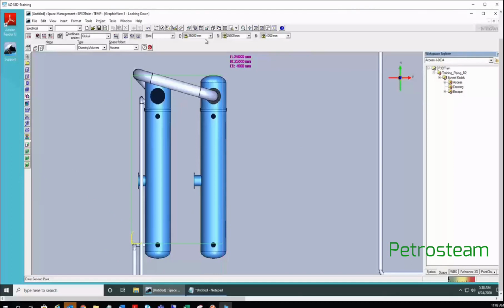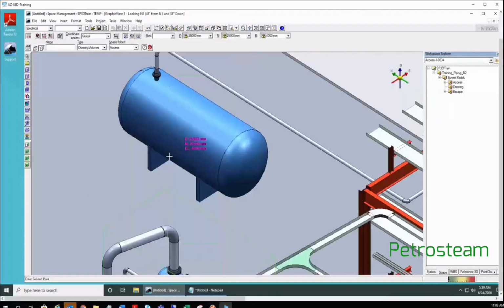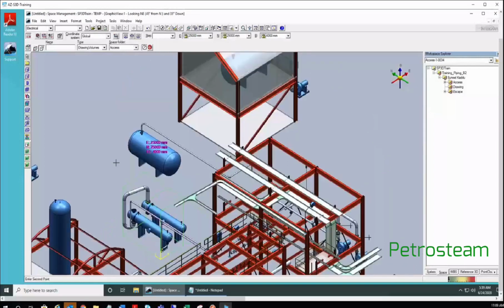So in that case, okay, let us finish this command. With this, we will see how to modify the volumes also. As it is, I will accept the second volume point also. The point is already highlighted. I will accept this point with left key. No value for name. Please enter a name.